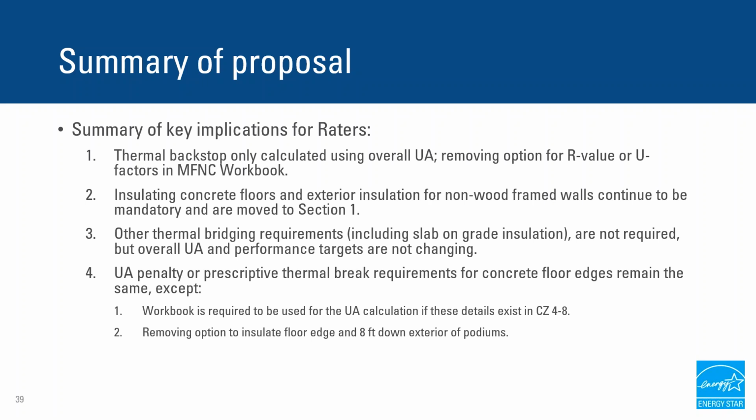And then finally, the UA penalty and prescriptive thermal break requirements for concrete floor edges remain the same, except that the workbook will be required for the UA calculation if these details exist in climate zone 4 through 8, and we're removing the option to insulate the floor edge down 8 feet on the exterior of podium walls to meet that thermal break.